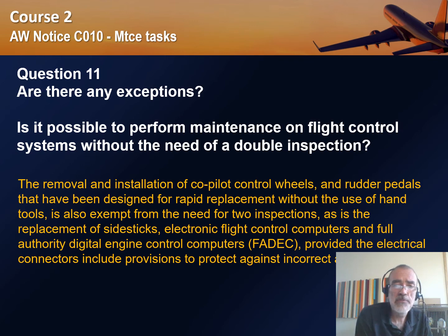Also, the replacement of side sticks, like in the case of Airbus family aircraft, which have this little side stick or joystick, the electronic flight control computers, and full authority digital engine control computers, also known as FADEC, don't need to be re-inspected, provided that the electrical connectors include provision to protect against incorrect assembly.